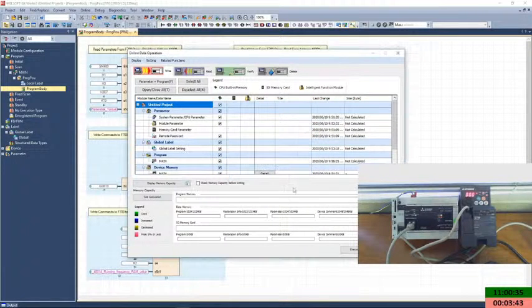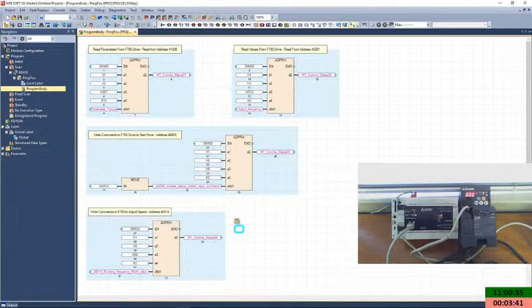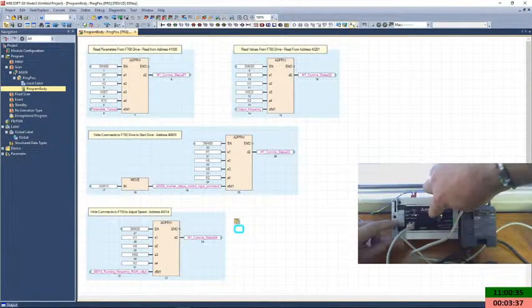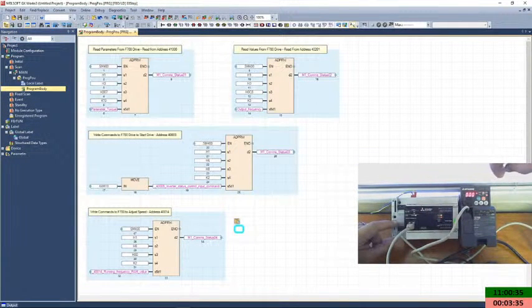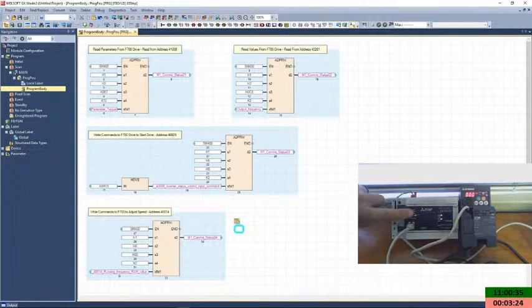And there it's just telling us we need to reset the PLC, which is something that I'll do now. And there I go, reset the PLC. You'll see the red light flashing, and then you turn it on. And as you can see, there are two lights, SD and RD. That's basically telling us the communications between the PLC and the VSD drive. That's always a good indication to show you that there actually are comms happening. Okay.